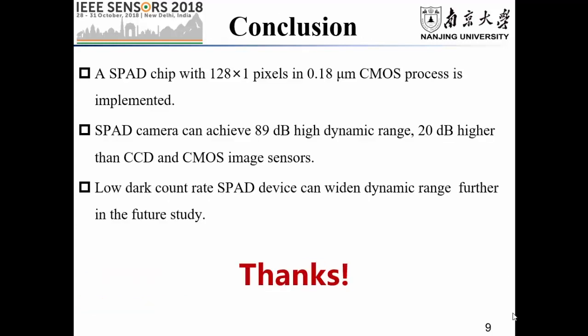Here is the conclusion. A SPAD chip with 128 multiply 1 pixels in 0.18 micrometer CMOS process is implemented. The SPAD camera can achieve 89 dB high dynamic range, which is 20 dB higher than CCD and CMOS image sensors. And a low dark count rate SPAD device can widen the dynamic range further in future study.